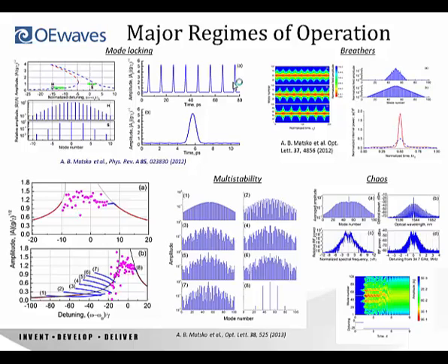Finally, a huge region of the dynamic range of this oscillator corresponds to chaotic generation of frequency combs. And I would say that early demonstrations, especially with broad frequency combs, were chaotic. Interestingly enough, if you look at optical spectrum analyzers that average a signal over time, those combs look pretty nice, but it happens because a spectrum analyzer, both radio frequency and optical, averages down the signal. So it is not necessarily possible to see that actually all those harmonics fluctuate in frequency and in power.